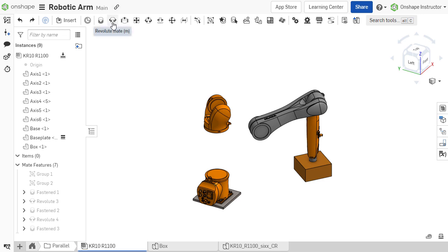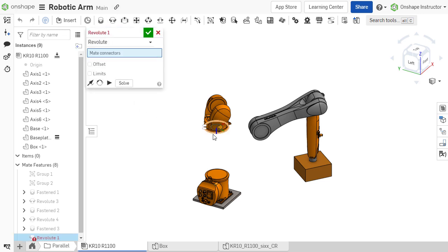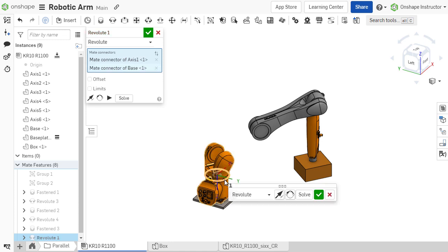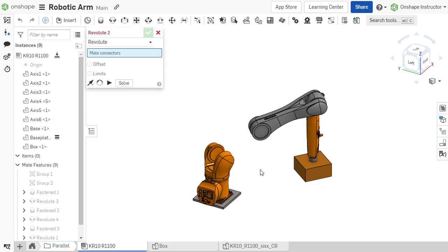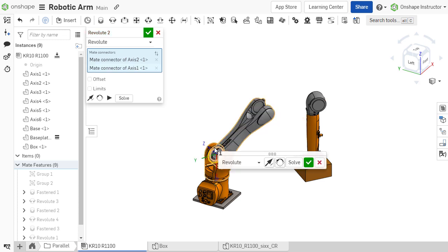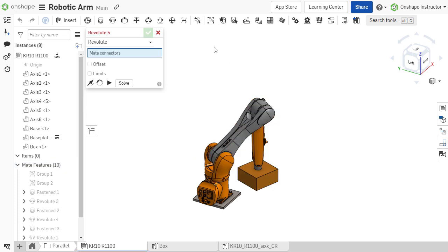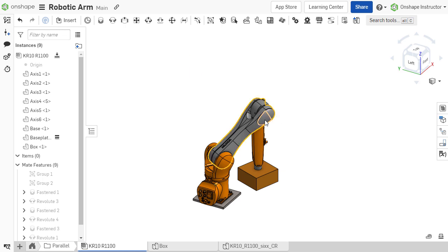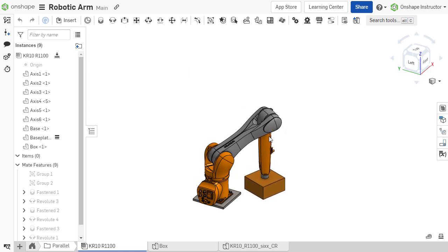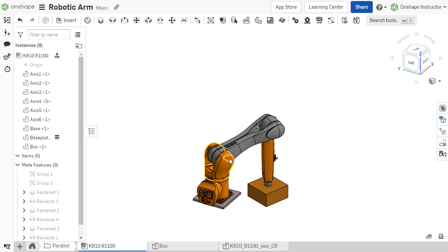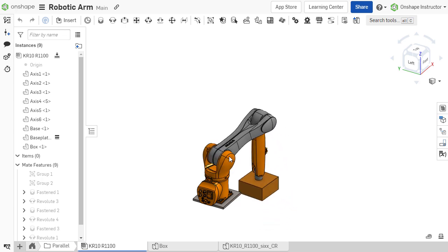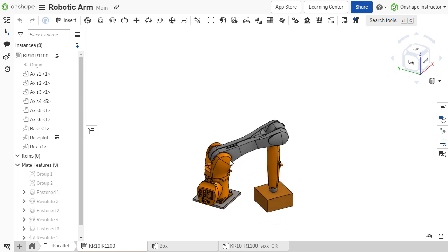In the Onshape Assemblies course, you learned how to use mates to define part motion in an assembly. Through the use of mate connectors, multiple degrees of freedom are defined with a single mate. Mates do not simply define the position of components, but also help visualize exactly how components move relative to one another in an assembly. The mates introduced in prior courses define motion between two parts.